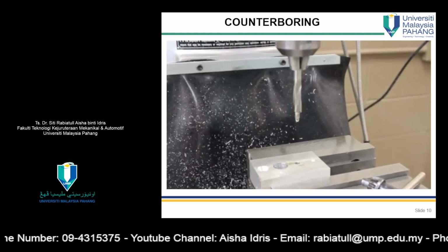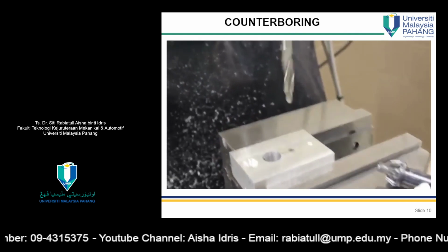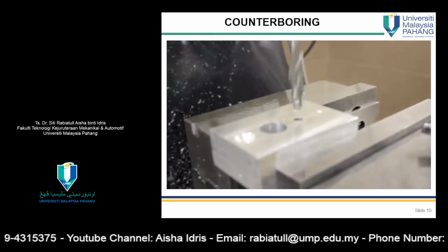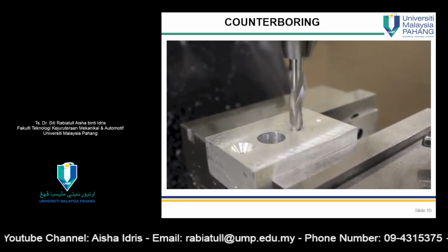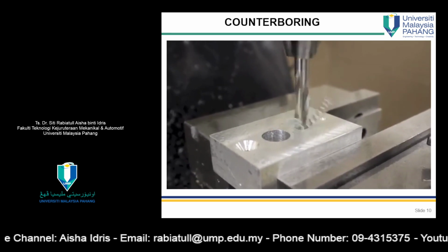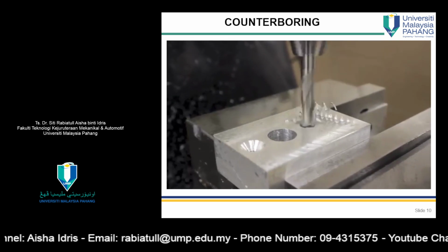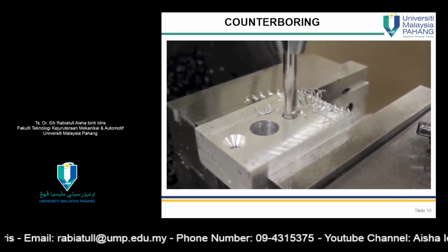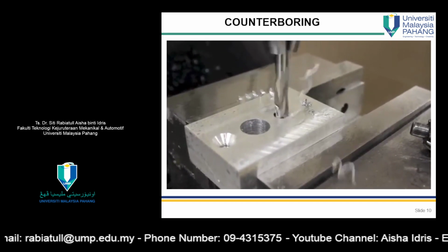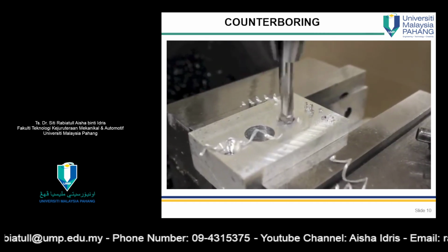Counterboring is often needed to recess cap screws in parts. A counterbore is machined after drilling has taken place and creates a larger diameter along the same axis as the hole that was drilled previously. The diameter and depth of the counterbore is determined based on the blueprint, or by the diameter and height of the head of the cap screw that will sit in place.